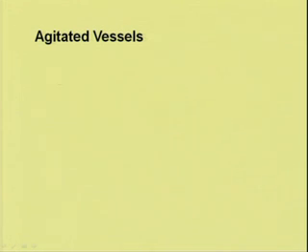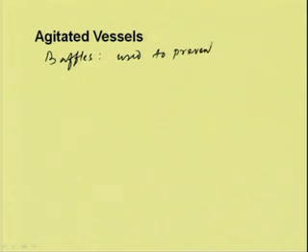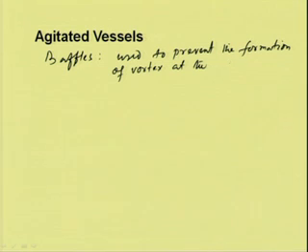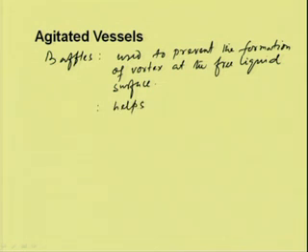Baffles are generally used to prevent the formation of vortex at the free liquid surface, and they also help to increase the turbulence in the tank.